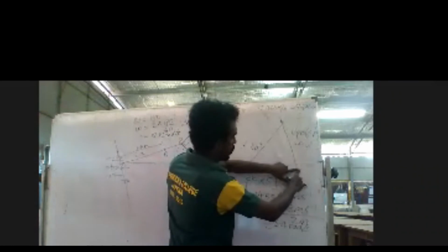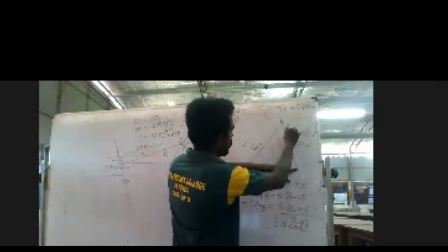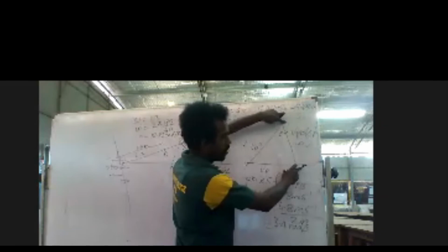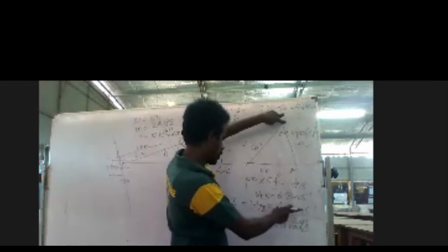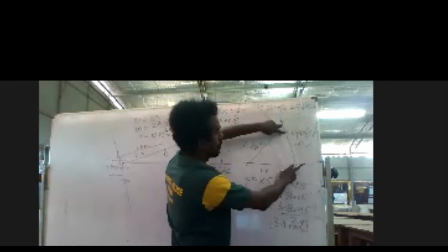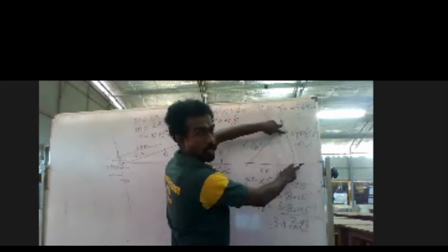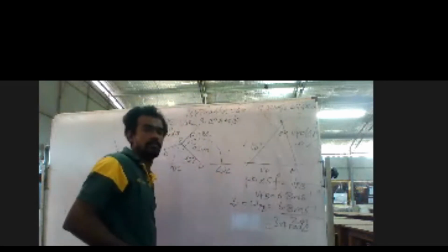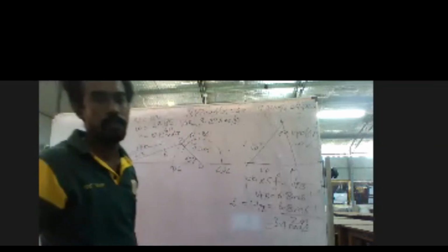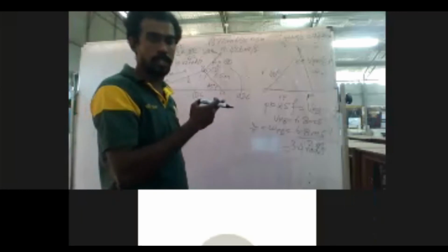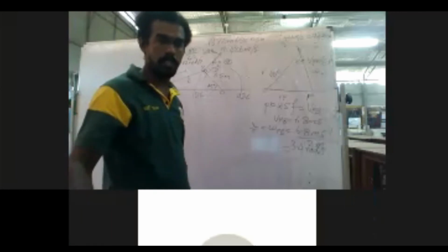So from P towards B, E is there somewhere, 4 is to 3. So if I consider this as 4 units, that is the 6.8 meter per second, right? Then the point E must be at 3/4 of the total length. So this is how we mark any arbitrary point on a length in the velocity diagram and find the velocity of that particular point.